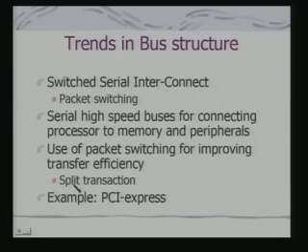We had discussed the basic concept of split transaction. You carry out a transaction, and if my slave is not currently able to do it, it remembers the identity of the master and later on carries out the transaction. This is the basic concept, very similar to packet switching.